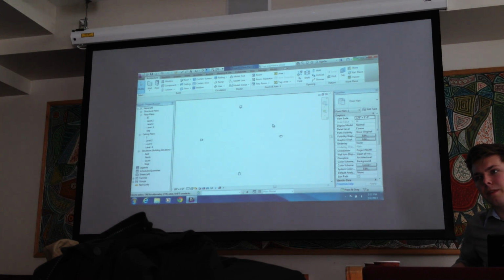The grid's useful if you want to have walls that go in certain increments, so you want to have walls that are all, let's say, 12 feet apart. So you create a grid of 12 feet for each grid line, and it will allow it to automatically snap to these grids. Or if you're doing a column system, and you want to have all the columns, let's say 6 by 8 feet, you can create the grid line so it's 6 in the x-axis and then 8 feet